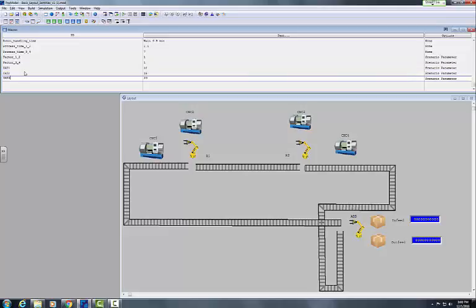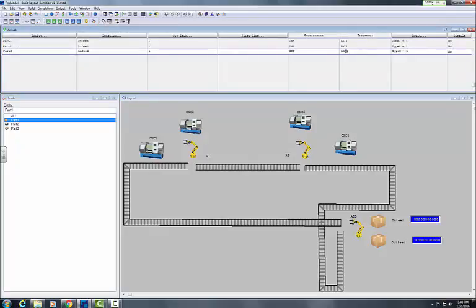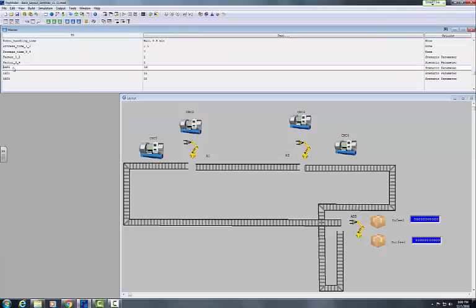IAT 1, 2, and 3. So these basically, if you remember, if you go to buildings and arrivals, we had something called the frequency inter-arrival time. And I told you here we had used macros. So going back to macros, these are the inter-arrival times for each one of the entities, and they're basically 10 minutes, 15 minutes, and 20 minutes.